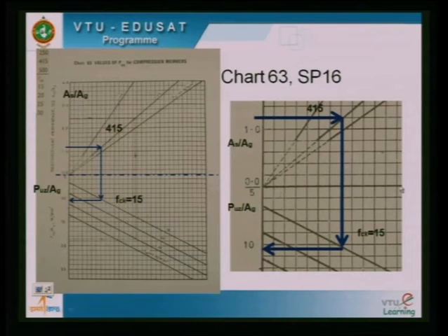And if you see from this particular reference line, we have these inclined lines. The top inclined lines correspond to the grade of steel, Fe 415, Fe 500, Fe 250, like that. The bottom 3 inclined graphs correspond to the grade of concrete. The first one is for 15, second one is for 20, like that it goes.